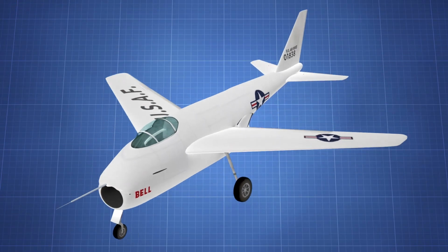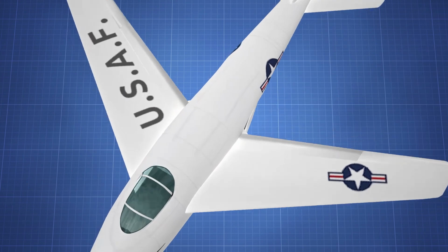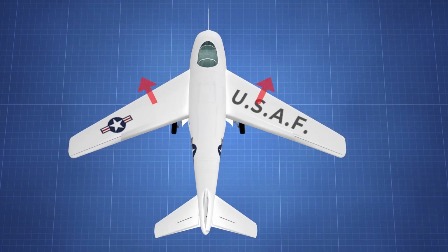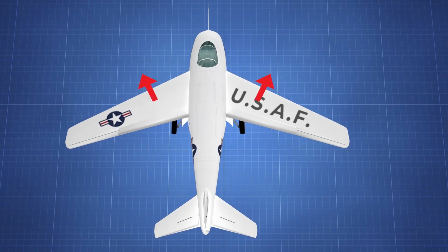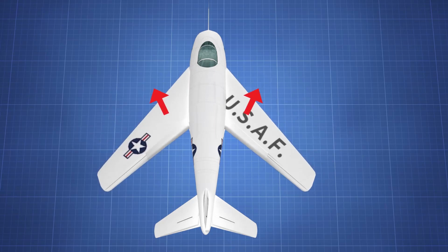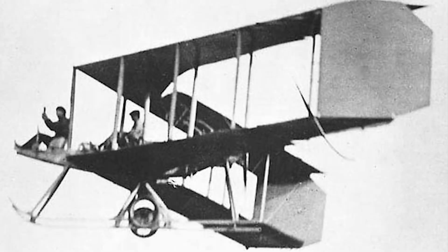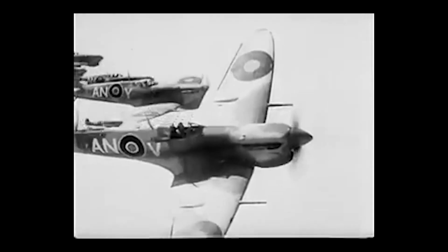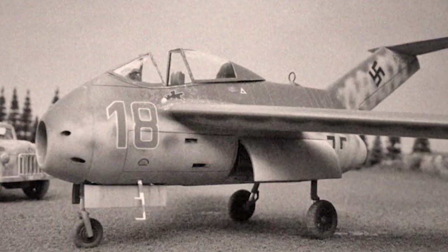For example, if we look at the X-5, which as I told you was the first airplane that had the ability to change the geometry of its wings in mid-flight, we see that the lift force would be applied at this point. When we change the angle of the wings, the point where the lift force is applied changes because the wing is moving. And that's why swept wings were already being used even before World War I because of the stability issue. But it wasn't until World War II, when there were already very powerful engines and planes were flying practically at transonic speeds, that they realized that angling the wings made the shock wave over the wing appear later.